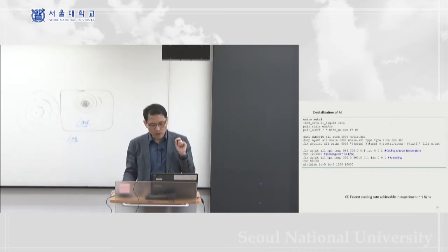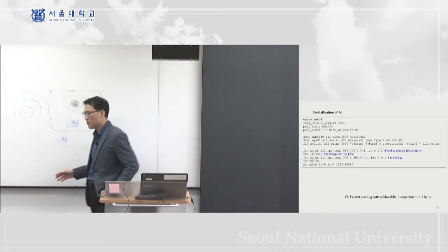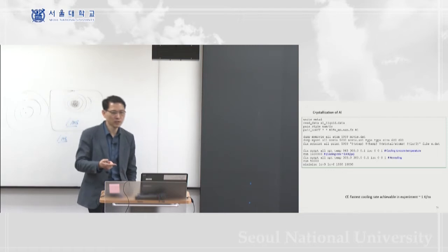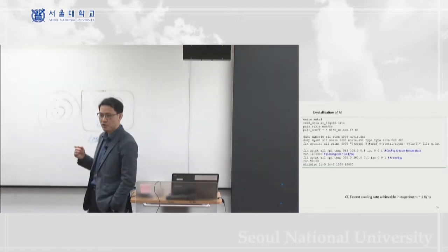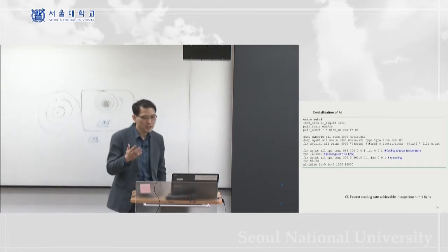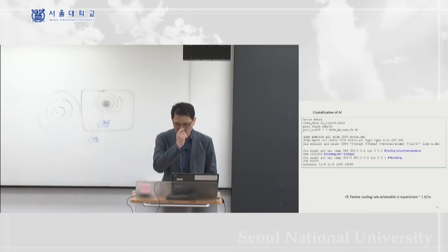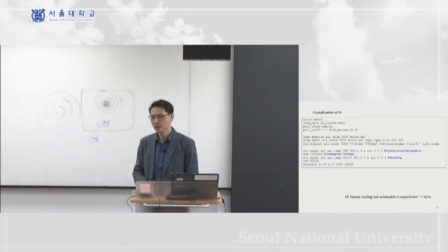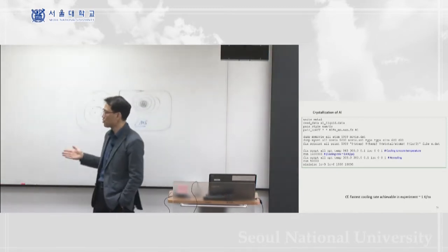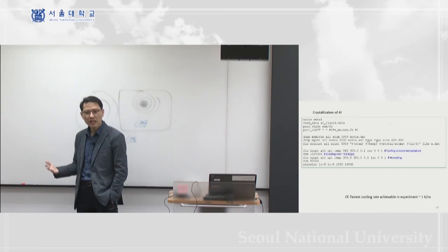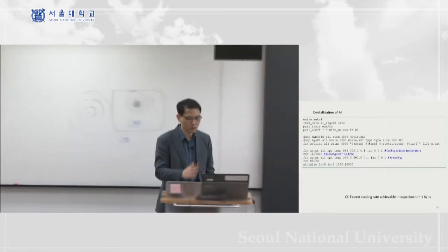But in some specific experiments, you can achieve extremely high cooling rates. This is used in obtaining the amorphous structure from the liquid phase. But even in that case, the cooling rate you can achieve is about 1 Kelvin per nanosecond. Of course, this is an extremely fast cooling rate. This means that in 1 second you are cooling down by 1 billion Kelvin, right? So this is an extremely fast cooling rate.